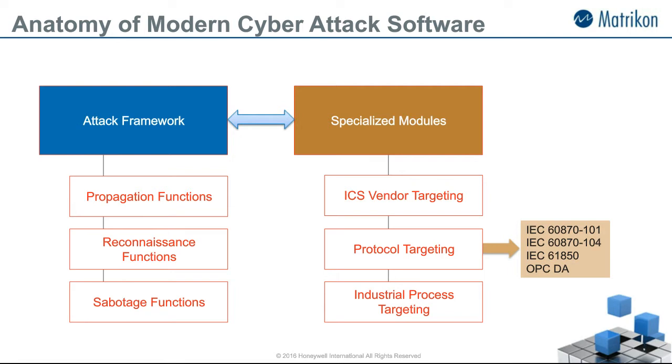So in this case, OPC DA was not used to actually eventually do any type of attack or even to do the writes, to try to control systems. But what it did do is, when an OPC client was connecting to an OPC server, when it connects to the server, it starts to obviously find out what type of items are available on that server.